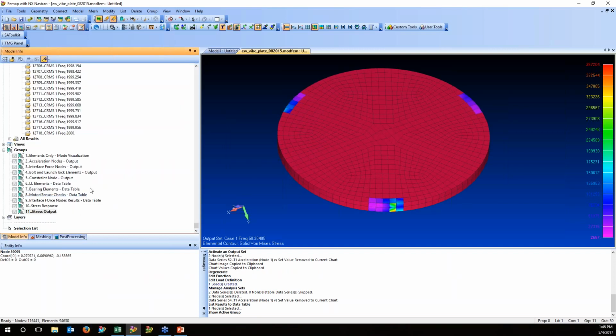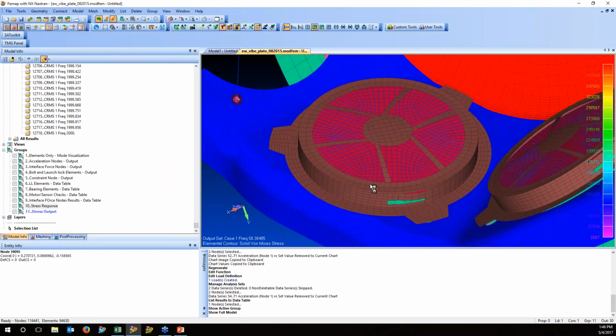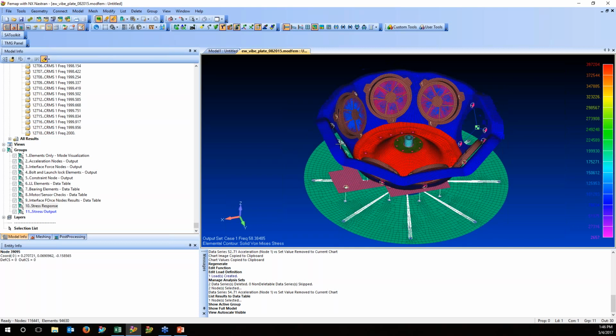So by looking at your RMS data and also your spectral density function, you're able to start determining your loads for your environments. From this data, you'd be able to use this for helping determine if your structure is going to be able to survive your load environment, or you can also use it for correlation to ensure that we're getting the proper data for the system.